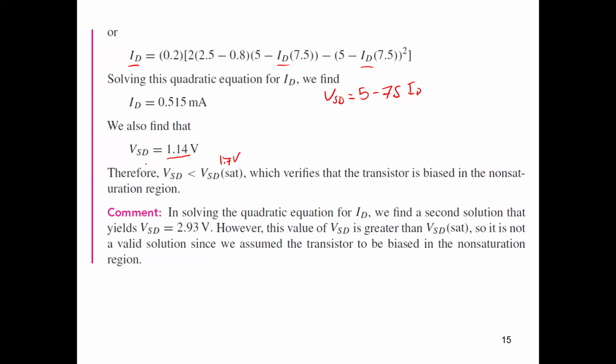For that, guys, we do not start the assumption in linear mode. Why? Because the linear mode assumption will provide a quadratic equation and you will have two solutions. One of them may be in the saturation and the other may be in the linear. So how can you guarantee now what solution is correct? We don't know.